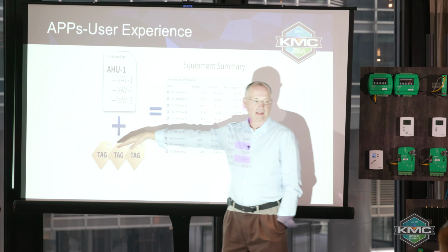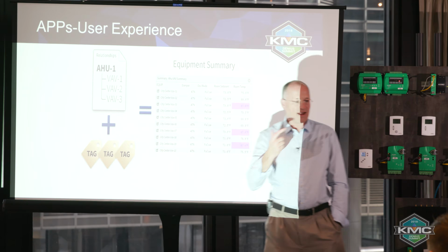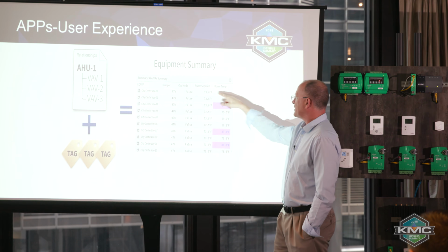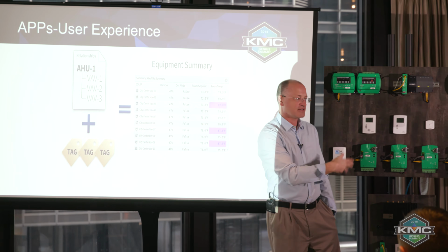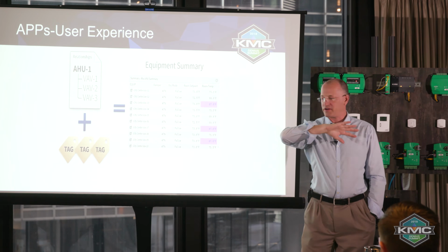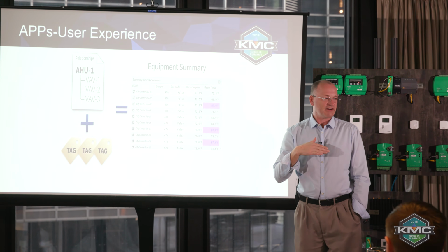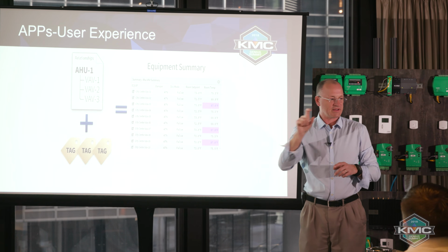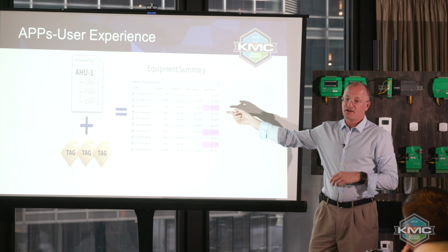It would resolve a little list of VAV 1 through 10, and then it would dive down into each of those VAVs and iterate the equipment name, the damper position, the OC mode. That's exactly what KMC Cards does as well on the opening screen. It looks at the list of devices, generates a visualization, and then you drill down to the cards to get the individual lines. This is all based on queries.